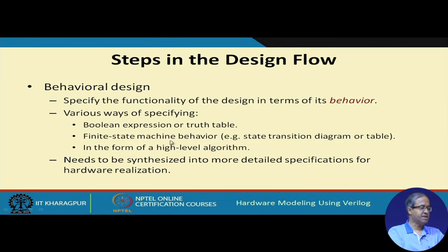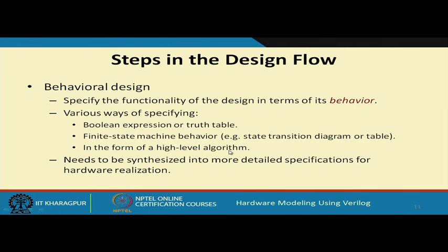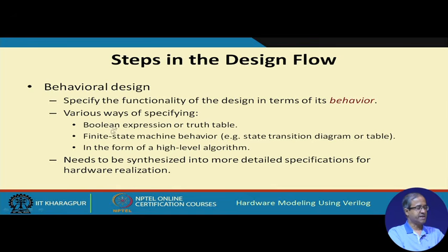If it is a sequential circuit, we can express it as a finite state machine, for example as a state transition diagram or as a state transition table, or you can even specify it at a very high level, just like a program written in C or C++ or Java. At a very high level of abstraction, you can write pseudocode just in the form of an algorithm. Now, during the design flow, this behavioral design has to be transformed, which is called synthesized, into a more detailed specification, as a result of which you will finally get your hardware.